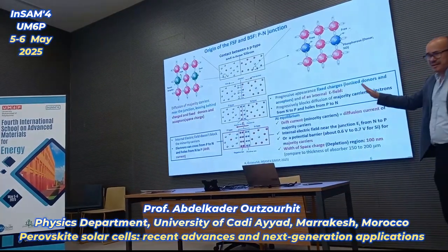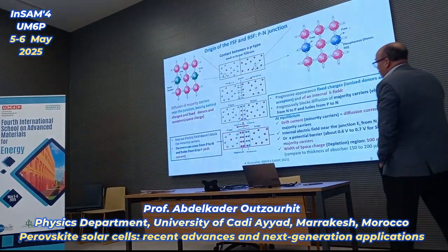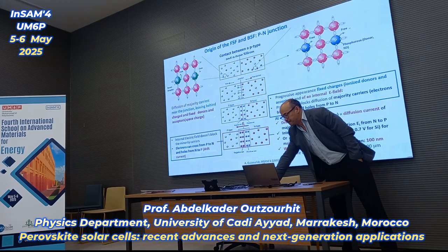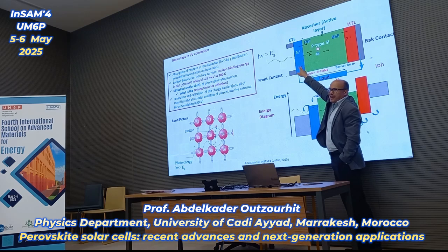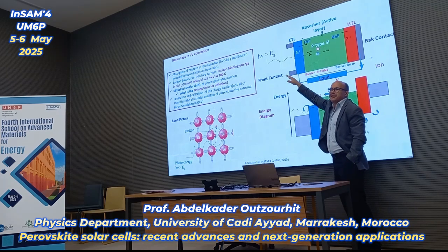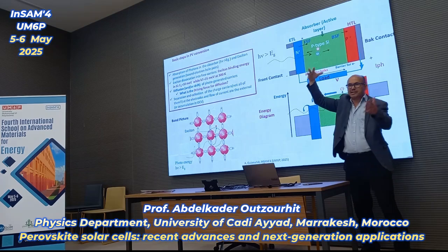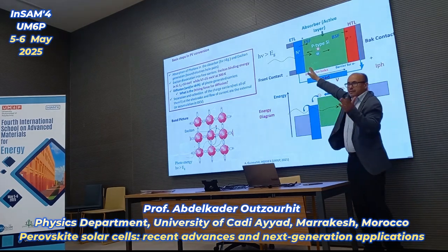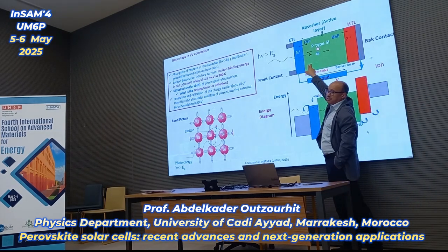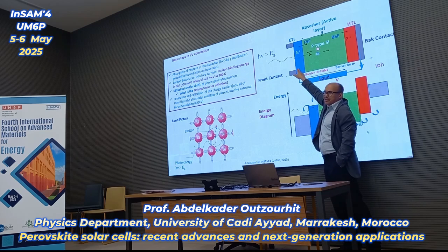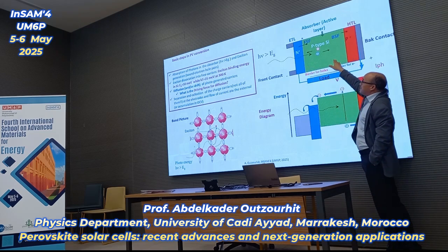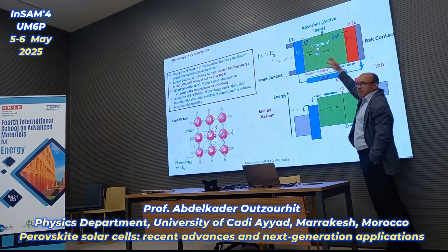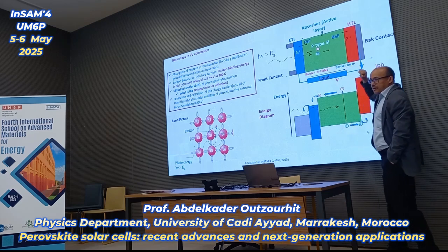This is very basic in order to understand the origin of the front surface field. This is basically an N-type and a P-type, but the plus means the doping density is higher here than in here. So for example, if this is 10 to the 16th, this should be 10 to the 17th or 18th per cubic centimeter. The same thing for the P plus here: it is much more doped, so we have more, for example, boron atoms here than in here.